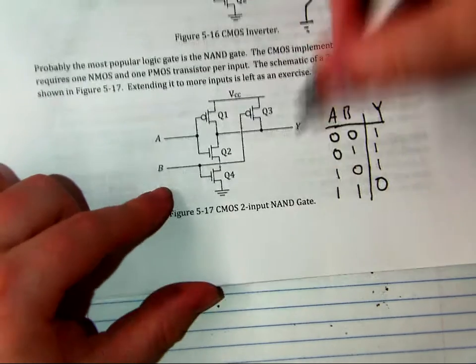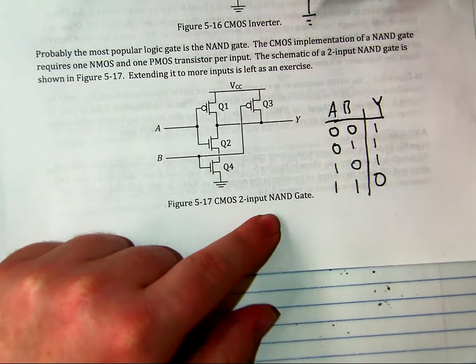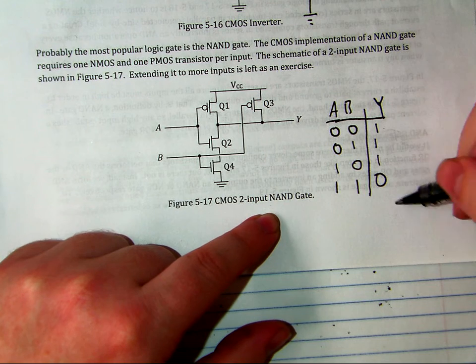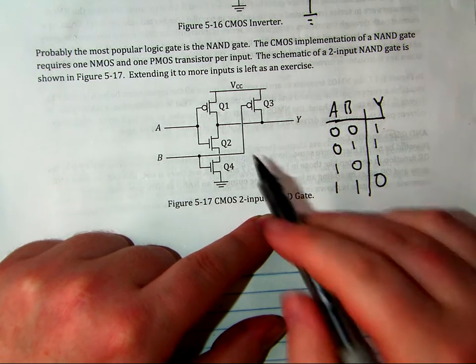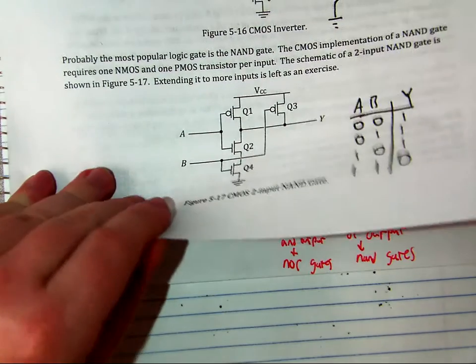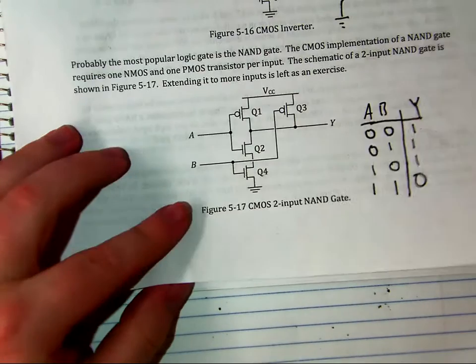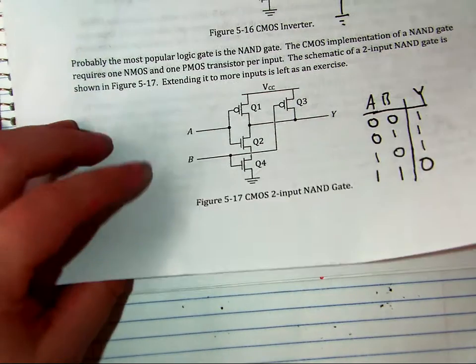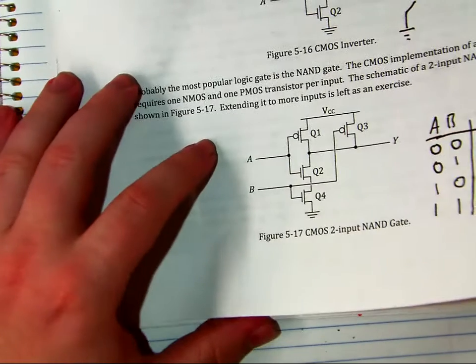So does this mean this is an AND gate? Well, yes, because an AND gate would be 0, 0, 0, 1. This is the opposite of that: 1, 1, 1, 0. So you can walk through gates like that and see if it functions like you'd think, and then start imagining ways that you might make a 3-input NAND gate. I think that's in the homework. It's pretty fun.